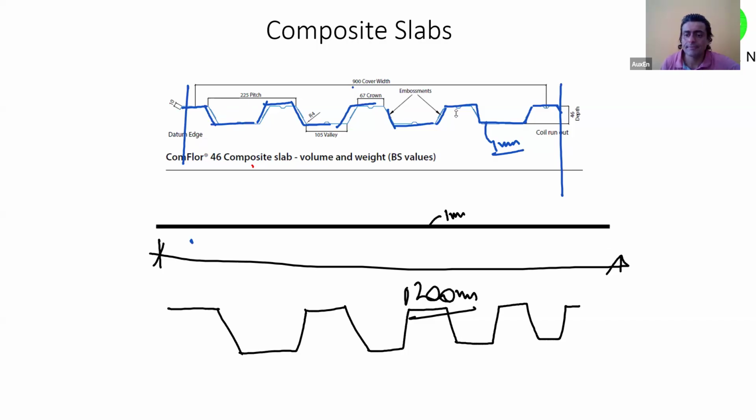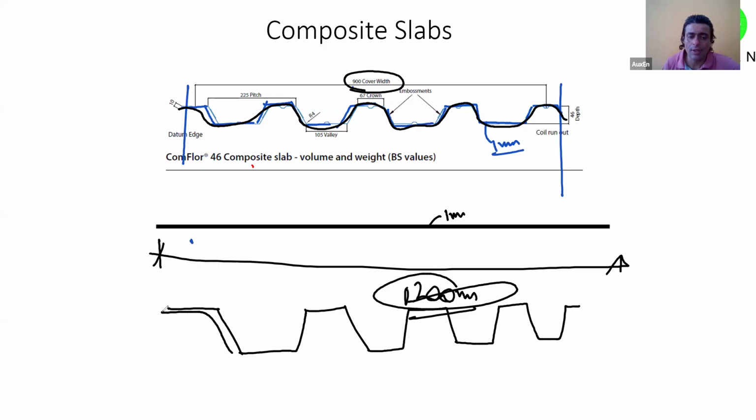I hope this is clear now. And the final width that you get, let's say you got a 900 mm width. Why did your width reduce? Because of course material was utilized in these crests and troughs. So if you were to add up the total length, it will be larger. So let's say it came out to be 1200, and after forming, the plan width remained whatever, 900 or 1 meter or whatever. Understood? Clear? So just one more point over here.